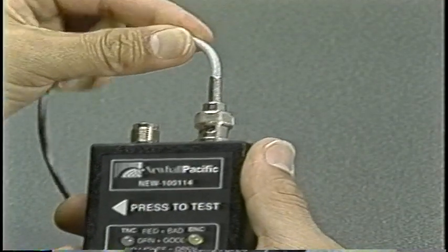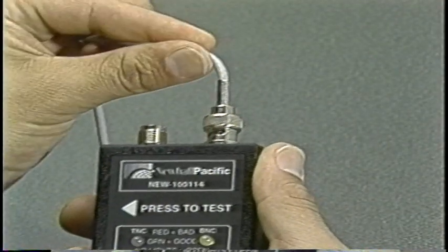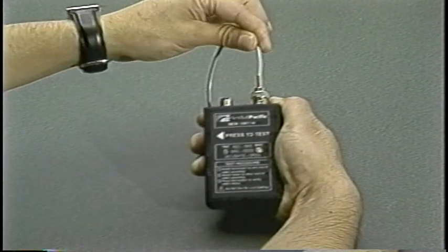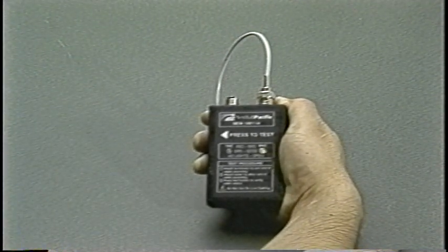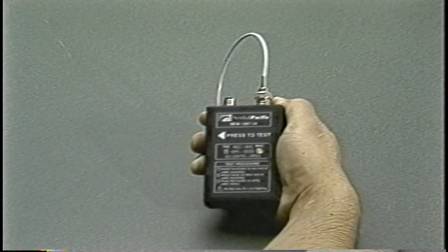Flexing the cable 15 to 20 degrees in all directions and a slight tug and compression on the cable jacket is all that is required to be reasonably confident that a connection is reliable. This technique is not a 100% guarantee, but it is a reasonable representation of the forces that a cable assembly will encounter in normal handling.